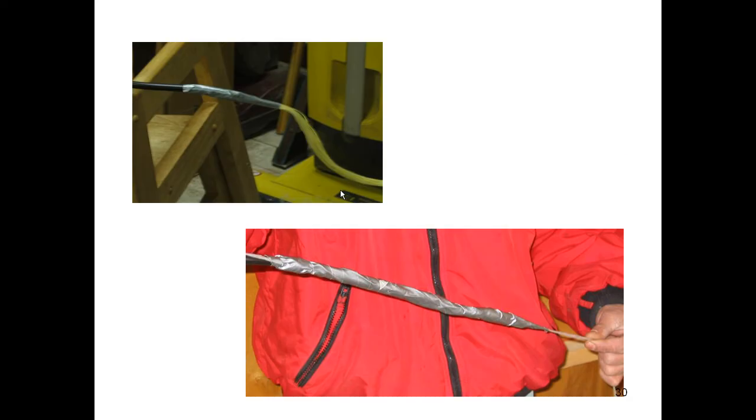Here you see, in the upper left-hand side, where we were getting ready to pull a direct burial cable through, we actually put it in a plastic conduit, but we're going to pull it 800 feet. What did we do? We removed 6 feet of the outer jacket. We removed the fibers underneath it, and then we've got the Kevlar. You see the yellow Kevlar hanging out. It's the Kevlar that you tie to the pull string, and that's what you pull, and the fiber rides along with it. Never pull by the fibers, never pull by the outer jacket, always pull by the Kevlar.